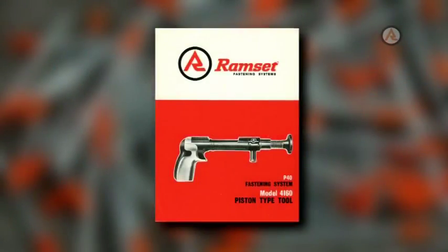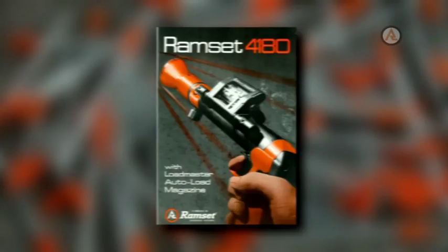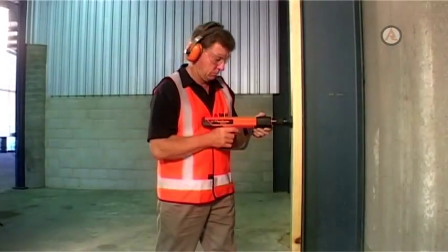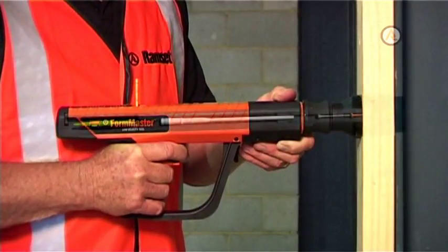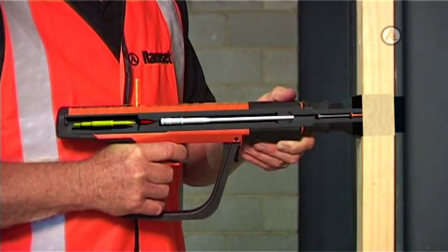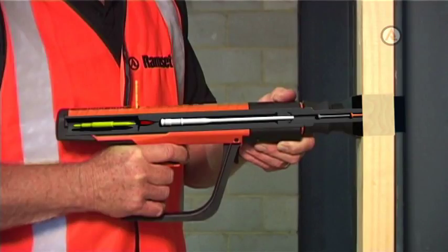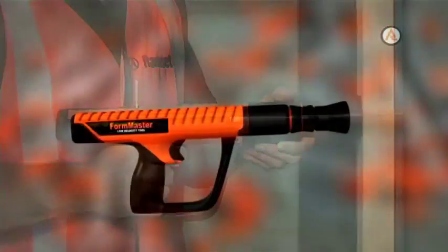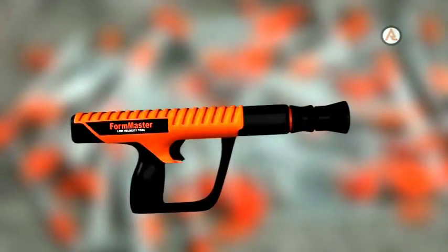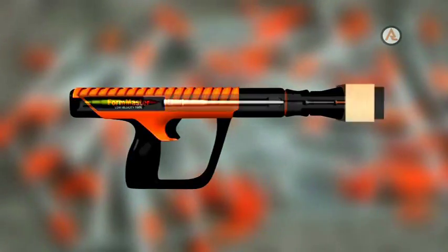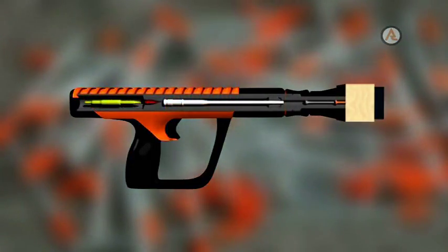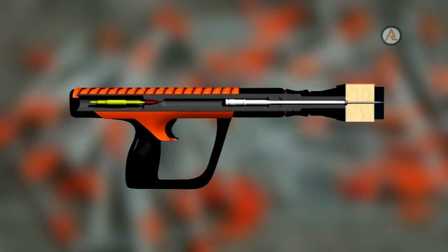Low-velocity tools were first introduced in the late 1950s. Low-velocity tools are designed whereby the energy contained within a power load is transmitted to a captive piston, which in turn transfers the energy to the fastener. This design limits the velocity of the fastener to less than 100 meters per second and thus greatly reduces the possibility of overdriving the fastener. The majority of any excess energy is contained within the tool by means of the captive piston.